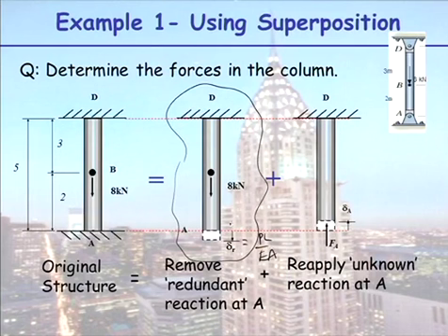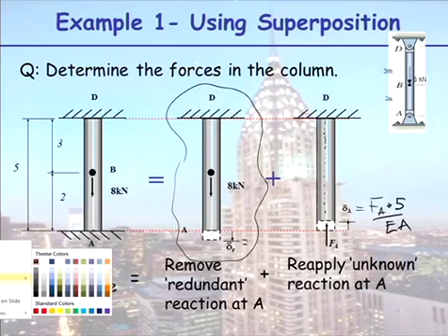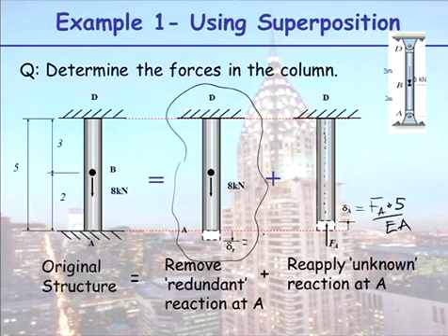Okay, and when I take away a support, I have to put it back. And again, I can calculate that shrinkage now. This time my P force will be FA, and this force here, can you see, is travelling up the entire length. So this time L is 5 on AE. Now back here, let me just rub that out. This value here, this deflection here, our force is 8 kilonewtons. And where is that force travelling? Is it travelling down here towards A?